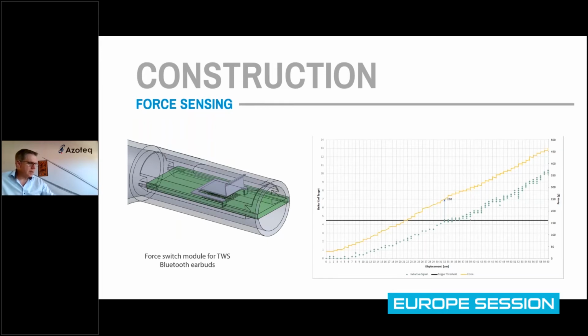And that train of pulses, you referred to a train of pulses. So if there's no activation, for every sample, the amount of pulses would be the same. Let's say a number of 500. So let's say every time it's 500. But then when the button is pressed, maybe only 300 of those pulses in the sample. And that is the way we set up the threshold.